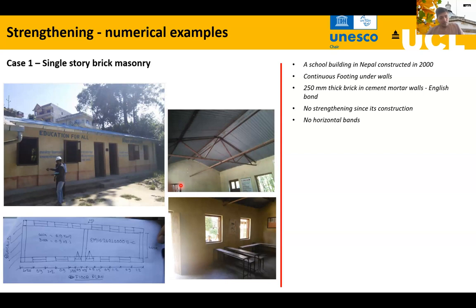Now we have seen some of the most commonly used techniques to strengthen walls, cross-wall connections, and the global building. Now we will see two examples supported by numerical analysis, and we will see in terms of vulnerability and fragility functions how we can improve the seismic behavior by strengthening.